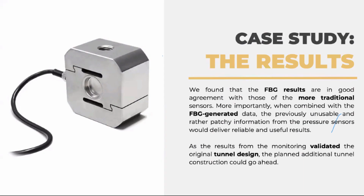The result basically was that we found that the FBG sensors that are placed are in good agreement with those that are more traditional sensors. More importantly, when combined with the FBG generated data, the previously unusable and rather patchy information from the pressure sensors would deliver reliable and useful results. As a result, the monitoring validated the original tunnel design, and the planned additional tunnel construction would go ahead.